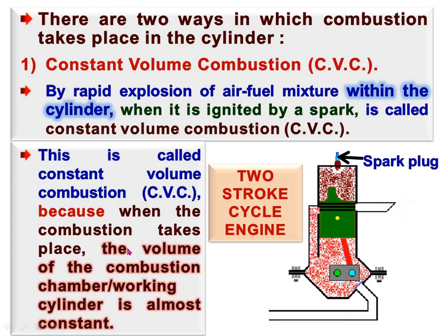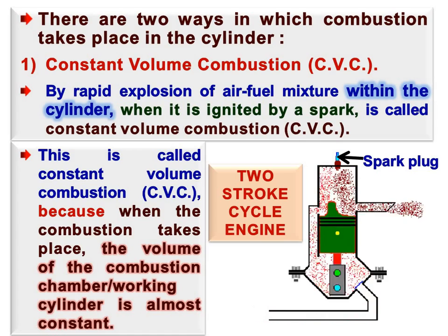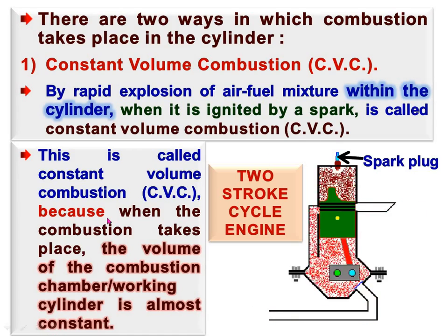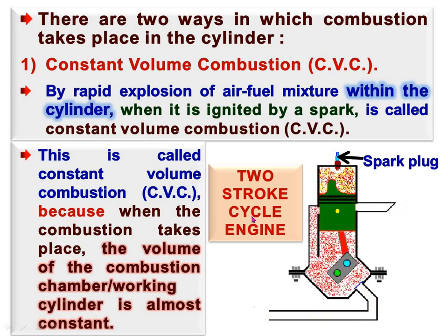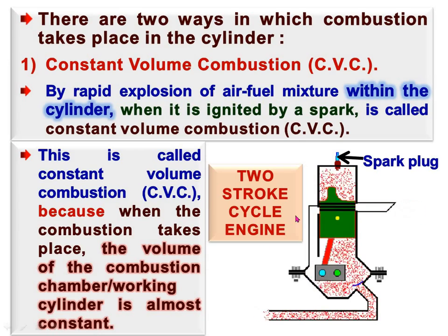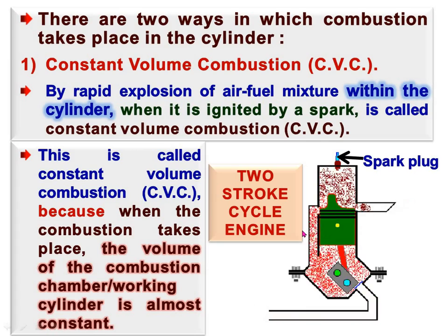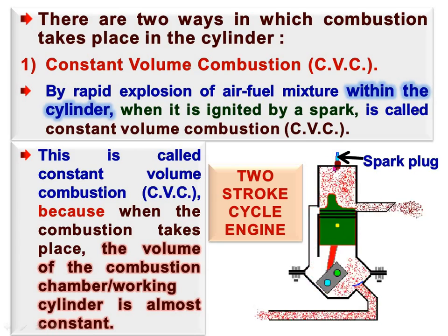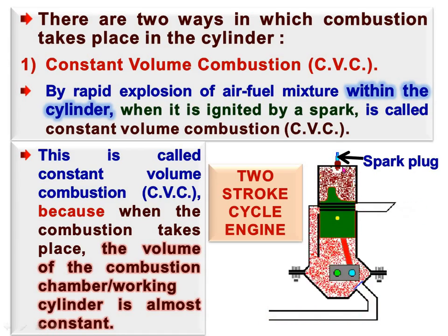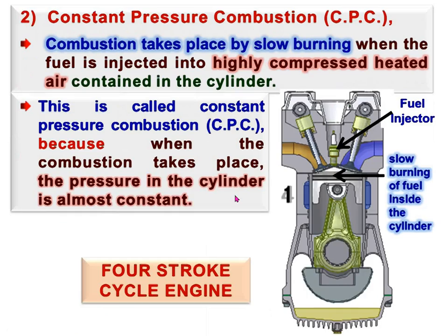Due to the rapid explosion of the air fuel mixture, there will be no increase in the volume. Generally in the petrol engine, or our two-stroke engine, constant volume combustion takes place. The ignition of the fuel is done by the spark plug in the engine.